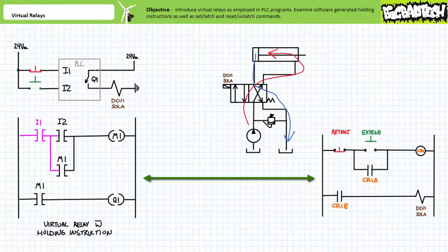Really, the only difference between this holding circuit as implemented by a PLC and one using a traditional hardwire relay-based ladder logic is that it necessitates fewer components and fewer wires. The relay in a PLC is a virtual programmed instruction rather than a real physical element that can and will break or be miswired. Additionally, should the need arise, the PLC-based system could be reprogrammed to perform alternate functions far quicker than a hardwire system could ever be physically rewired.